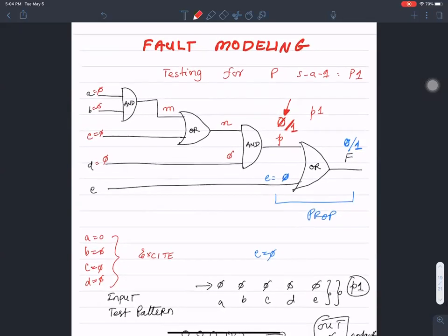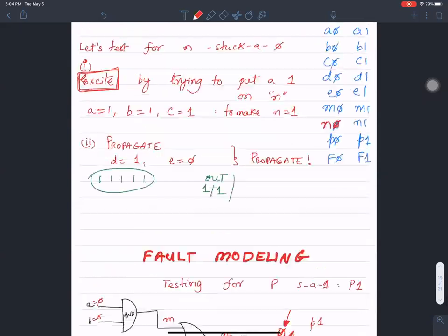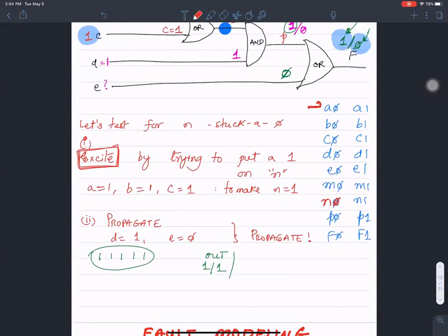You understand the notion of fault modeling, correct? So you list all the faults possible. Let me go back here. So A0 through F1, this is the complete exhaustive list of all the faults possible. Okay, then you go about eliminating each fault. Is this fault present? What input do I have to apply to test for this fault? So on and so forth.